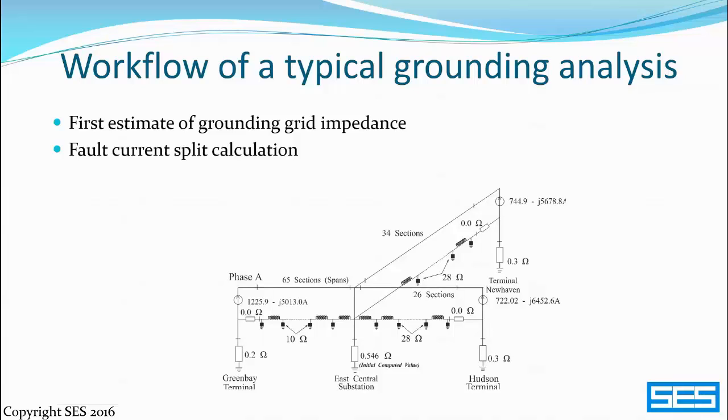Considering this effect will greatly reduce the fault current at the substation, especially since inductive coupling between the phase and shield wires helps push current along in the opposite direction of the fault. In the case of cables, the effect can be quite strong, leading up to 90% of the current not going into the substation grid and going back to the source via the sheath.